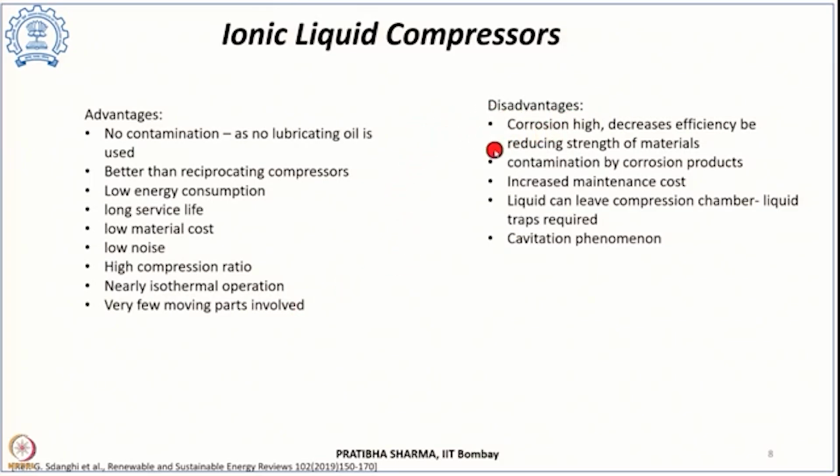But the disadvantages associated with ionic liquid compressors are that ionic liquids can cause corrosion, and there are high risks of corrosion. Because of these corrosion challenges, the strength of the material could reduce over a period of time, and that can decrease the efficiency of these compressors.